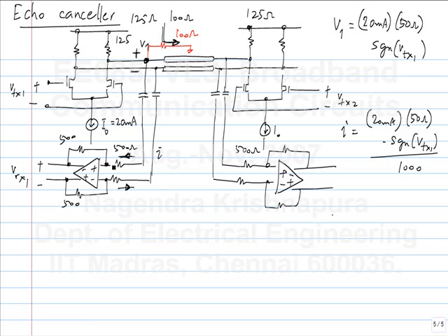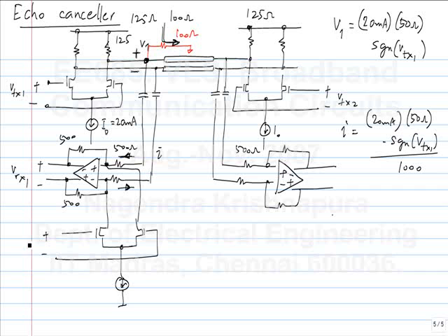So this diagram is getting more and more messy. Now I apply, firstly, which polarity should I apply it in? Which side should be plus? In this case, I think this is the right one, because when it's plus, the current that is flowing in here should be drawn out of this one. Okay, so this is VTX1. This may be the opposite sense of how the diagram was drawn, but that's okay. As long as you know how to get the sign, that's fine.